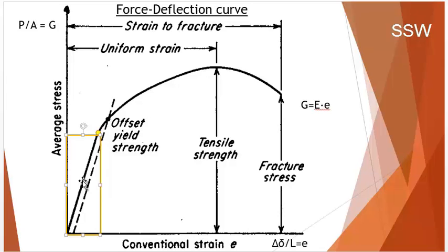Here Hooke's law is applied, and that is why we have a linear relationship between stress and strain. As you can see, these two assumptions may be confusing, but keep in mind that the first assumption derives from Hooke's law. Most materials have to follow these rules. In most cases, we are working with loads and stresses that are in this elastic region.